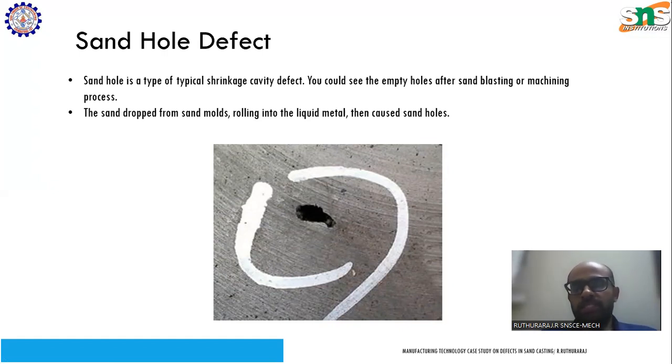The parting sand is to provide a smooth surface and to also prevent the reaction of surrounding sand with the molten metal. So parting sand is a slightly soft and smooth finish material. What it does is that it prevents the larger sand grains from interacting with the molten metal.